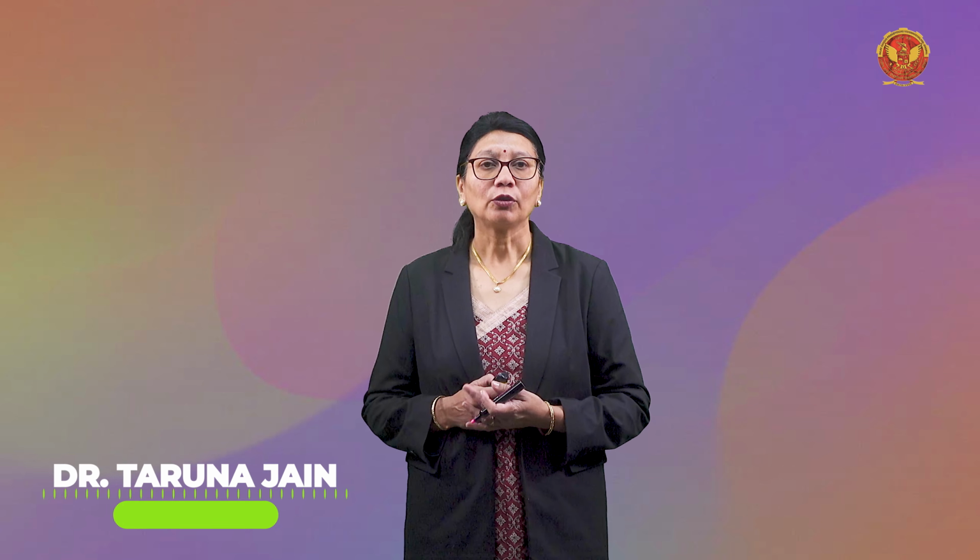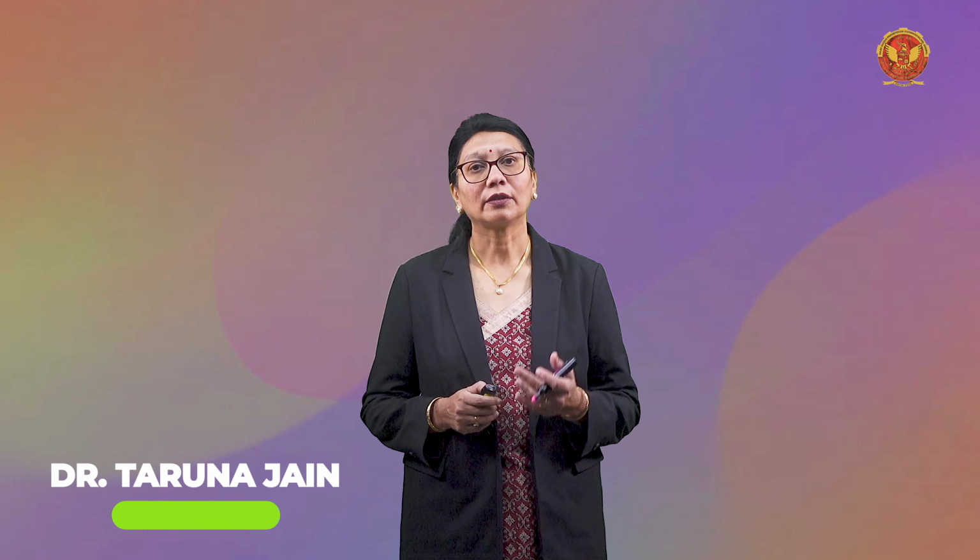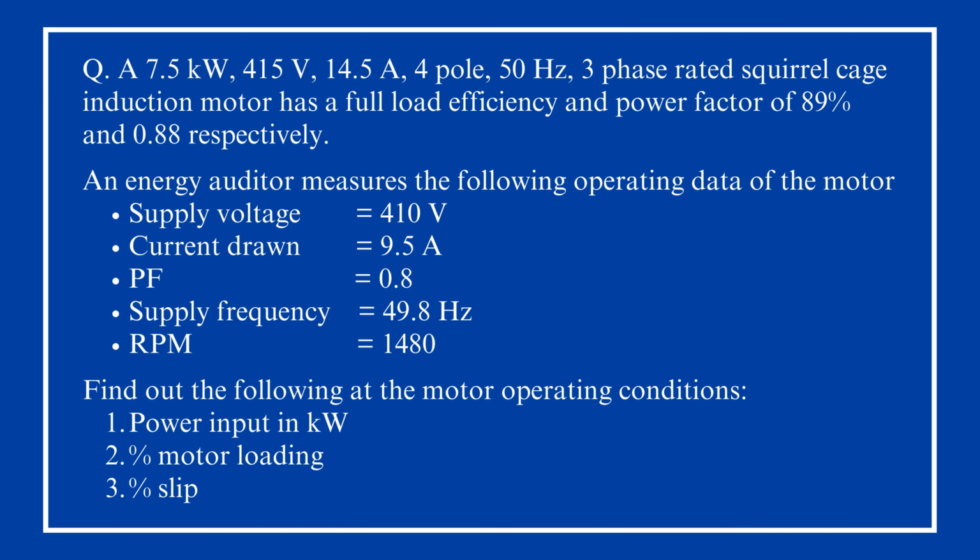जैसे कि हमने मोटर एफिशिएंसी के बारे में डिस्कस किया, तो मोटर एफिशिएंसी के बेस्ड जो भी डाटा है, पैरामीटर्स हैं, उनको कैसे कैलकुलेट करना है, लेट अस सी विद द हेल्प ऑफ दिस न्यूमेरिकल। यहाँ हमारे पास है a 7.5 kilowatt, 415 volt, 14.5 ampere, 4 pole, 50 hertz and 3 phase rated squirrel cage induction motor। इसके अंदर फुल लोड एफिशिएंसी दी हुई है 89% and power factor is given as 0.88 respectively.